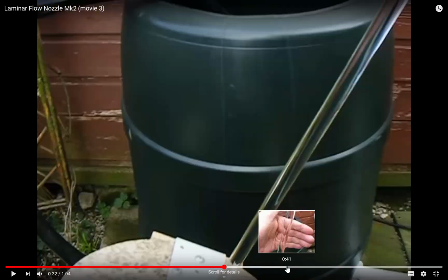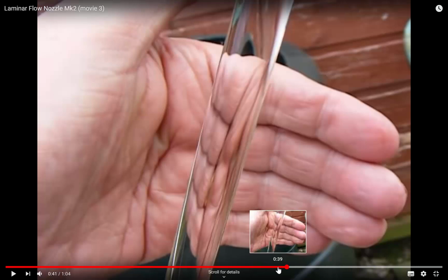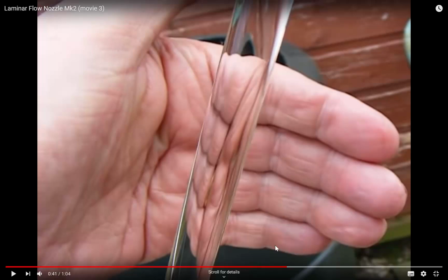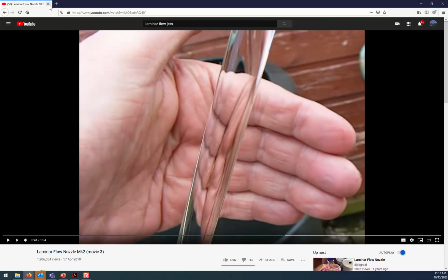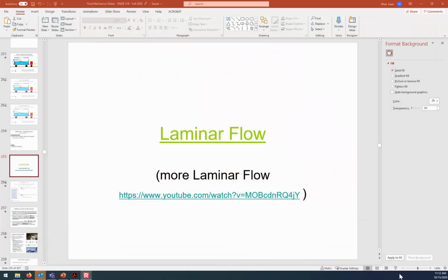And there is a similar thing to this in the Detroit airport, where they've got a bunch of these set up, and you can see the water dancing around between different puddles, and the streams themselves appear to be stationary over time. Both of those are possible only when the flow conditions are laminar and the velocities are very low. Otherwise, there would be too much turbulence.